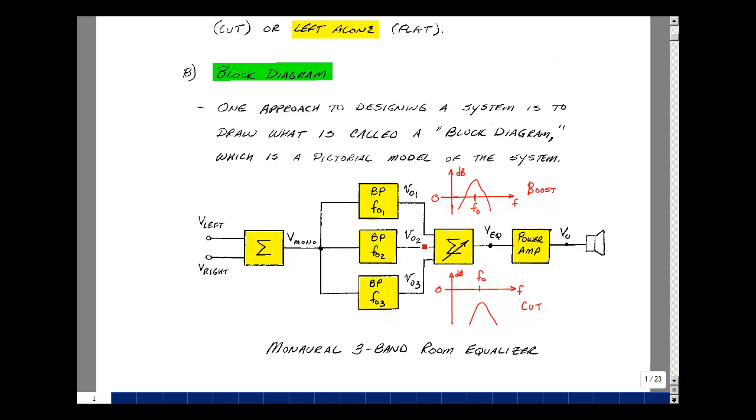I'm going to add those together with a summing circuit with 3 pots, and those pots will allow us to adjust the volume for that band of frequencies. Now the summing circuit is going to put our music back together again with some bands louder, some bands softer, some bands maybe not manipulated at all. And lastly, we'll put it through the power amplifier we designed in our microphone lab, and then drive a speaker with it.